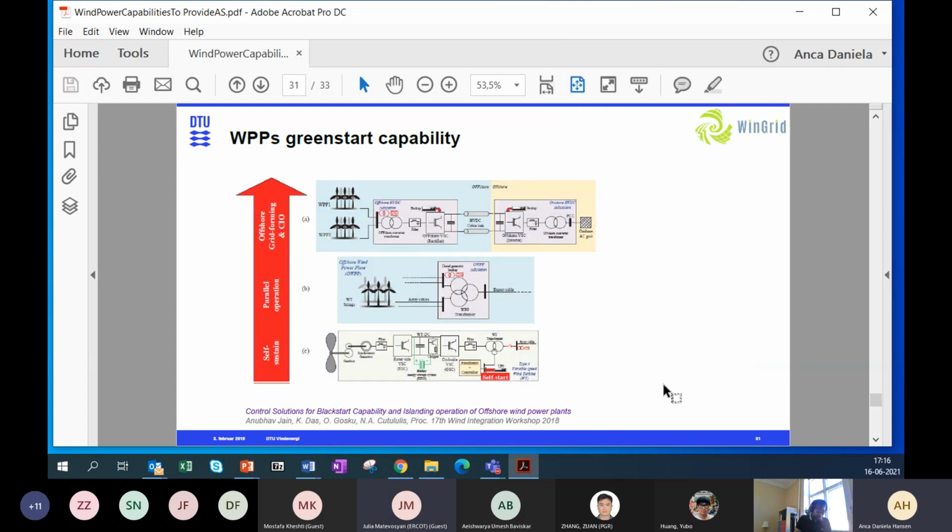Small help. Yeah, that's the reason why I asked. I've seen they tested some wind turbines for Blackstart in Scotland, and they use a small diesel there. I think that is also the major concern for offshore wind farms, because putting in diesel, one thing is that you need to refuel it, but it also has challenges in terms of safety and security. So that also increases the insurance cost.